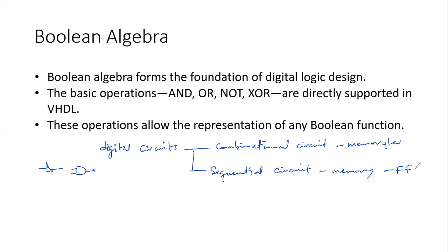And there are a few details we want to consider about combinational circuits, in terms of their connection. We already mentioned in the previous notes that every circuit element is itself combinational. Every node of the circuit is either designated as an input to the circuit or connected to exactly one output terminal. They also have that the circuits contain no cyclic parts, meaning every path through the circuit visits each circuit node just once.